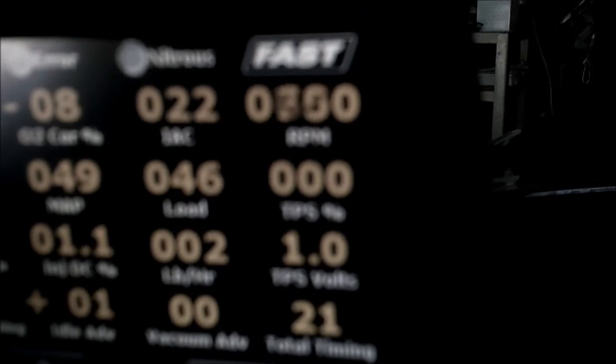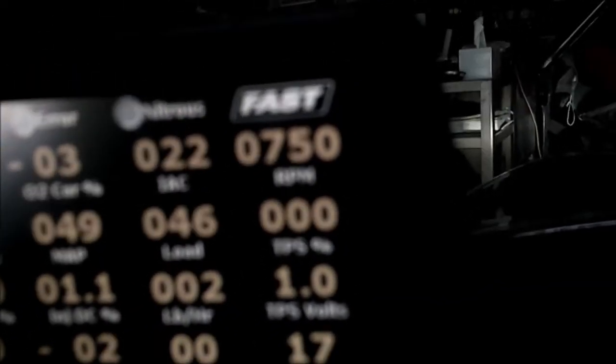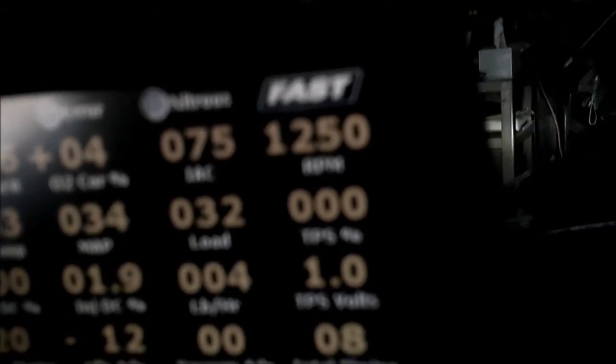Okay, you can see it's at 17. That's the motor that's regulating the idle speed. So if I turn the headlights on, you'll see that number go up. Right? If I turn the rear window defogger on, maybe the air conditioning, you see it really open up there, and then it wants to bring the idle down, so now it closes the pintle back down, blocks the flow.